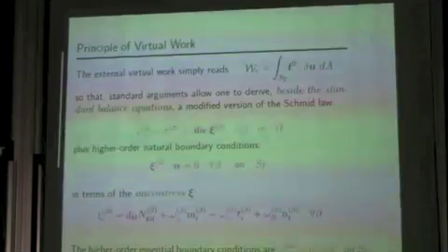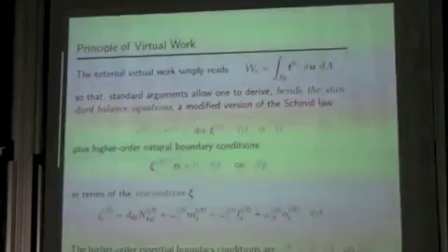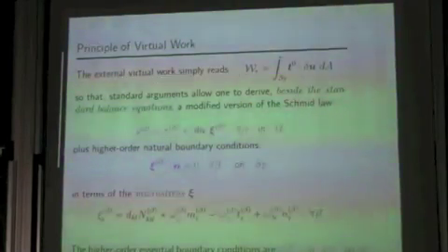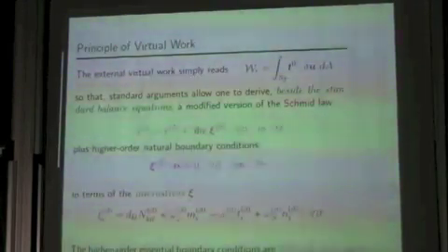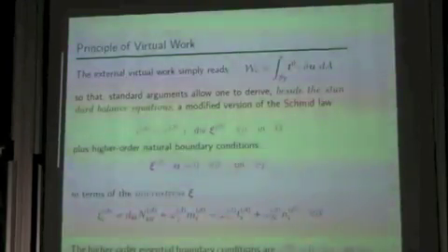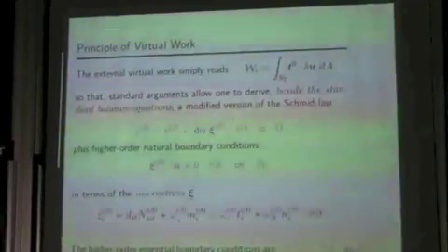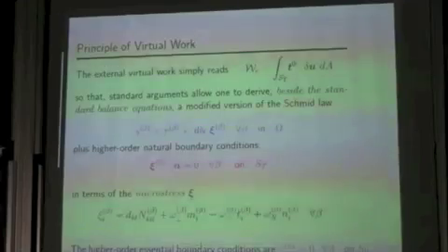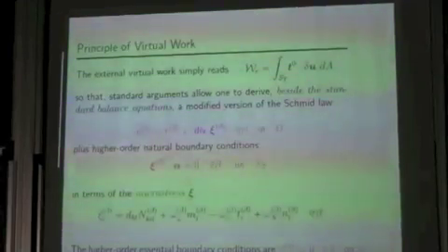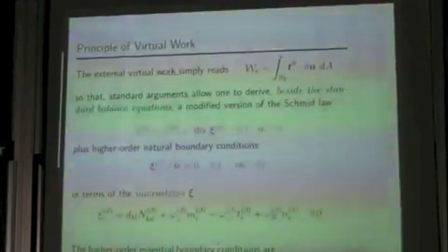And so the external virtual work is standard because we just use higher order homogeneous boundary conditions. So either the slip is 0 when dislocations pile up, or the higher order traction is 0 when dislocations can just exceed the boundary. In our benchmark, of course, our higher order boundary condition just says that the slip has to be 0 on the boundary where dislocations pile up, and this delivers this size effect.